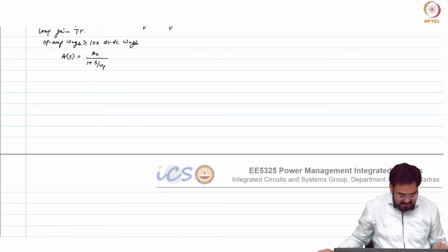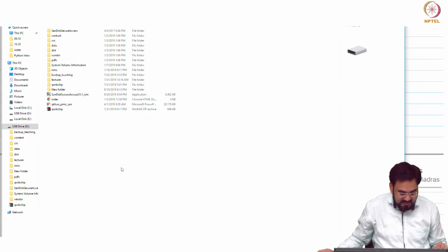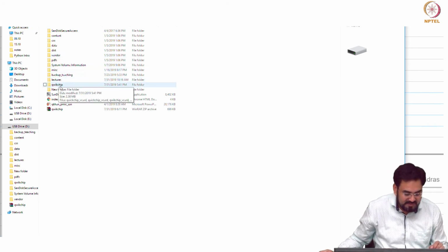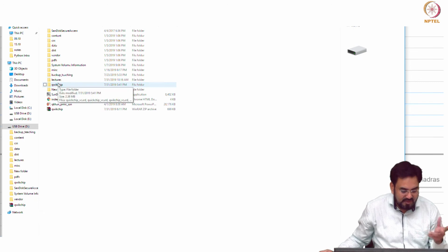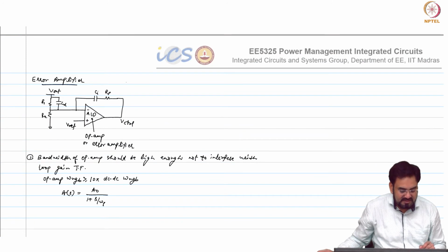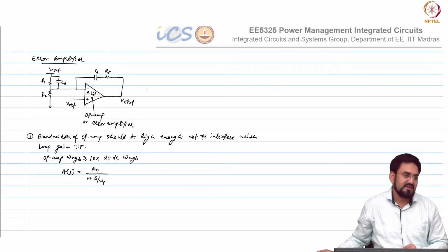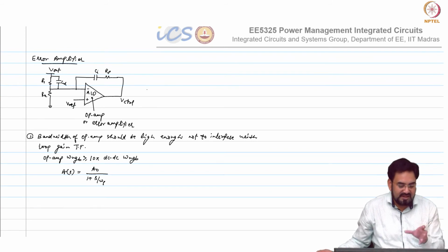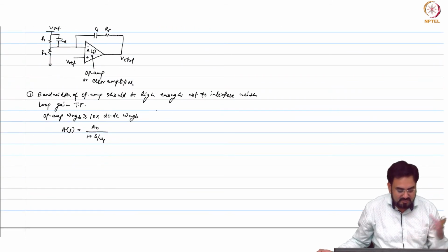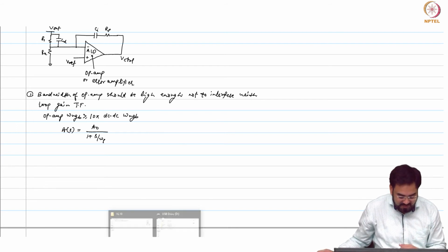One thing I mentioned yesterday was about the resonance, so I'll just show you what happens. If you want to really see why this is occurring, you can just replace this op amp transfer function with this and then derive the compensator transfer function again, and you see how it affects it. You will see some additional resonance frequency in your loop gain. So one resonance is coming from L and C, and another one will come from this one due to the limited bandwidth of your op amp.